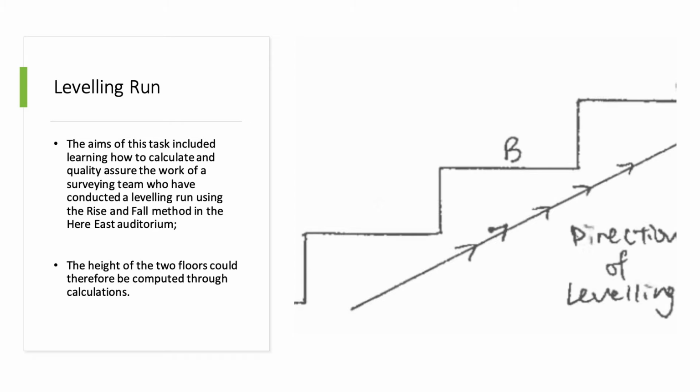One of the first tasks of the Scenario Week is the leveling run. Through this task, we were able to broaden skills in calculating and quality assuring the work of a surveying team who have conducted a leveling run using the rise and fall method. This was done for the Here East Auditorium in order to compute the height of the 2 floors with a given zero value of the ground level.